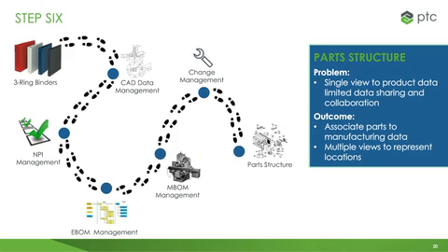We introduced document association through WT part use. We were now associating CAD, PDF, and Office documents to our WT parts inside of PDM Link. We associated describing documents in all parts of the MBOM: labels, stickers, testing, label placement, packaging configurations. We even showed shipping how to load a truck and how to stack in a warehouse.